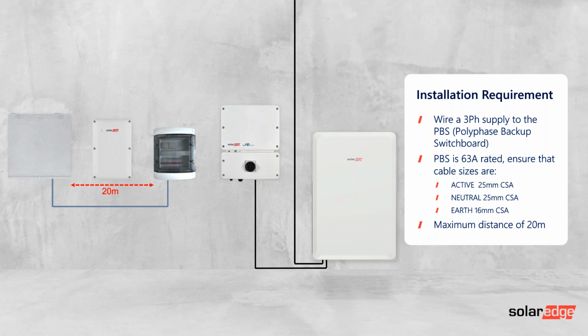So the home hub inverters, if you've got a 10 kilowatt inverter there, you've got to be running about 45 amps in backup. So you've got to make sure that there is sufficient cable size for the earth fault loop impedance, basically to be able to get back to the main MEN connection, which is still retained in the main switchboard.